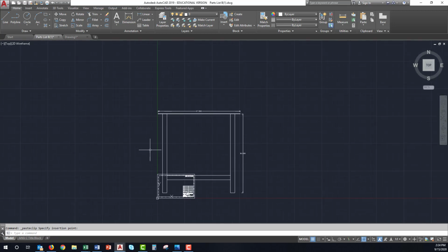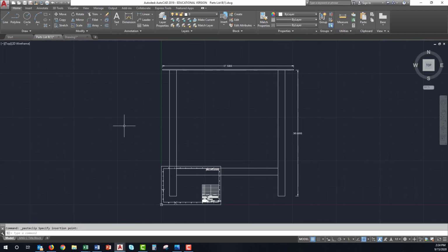So what happened? Well, when we're drawing in AutoCAD, we're drawing everything pretty much one-to-one. When we make this line and tell it it's 37.5 inches long, it believes us. To print this off full size, I would need a piece of paper big enough to hold that. But it knows from the importation process of this title block, this drawing block, that we've told it this is only 11 by 17. So we're not speaking the same language, right? We're drawing our stuff one-to-one, and yet we're going to have to scale down to get it on our drawing.